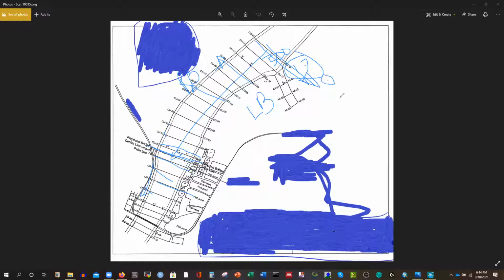So we'll provide Q, flow rate or discharge, as a boundary condition, and at the very downstream, if it is there, we'll provide water level, right? For Q, we'll calculate the 100-year return period of Q. We have historical data from different observation stations, and then we'll use the Gumbel extreme distribution method to calculate this 100-year return period of flow rate, and same for water level.